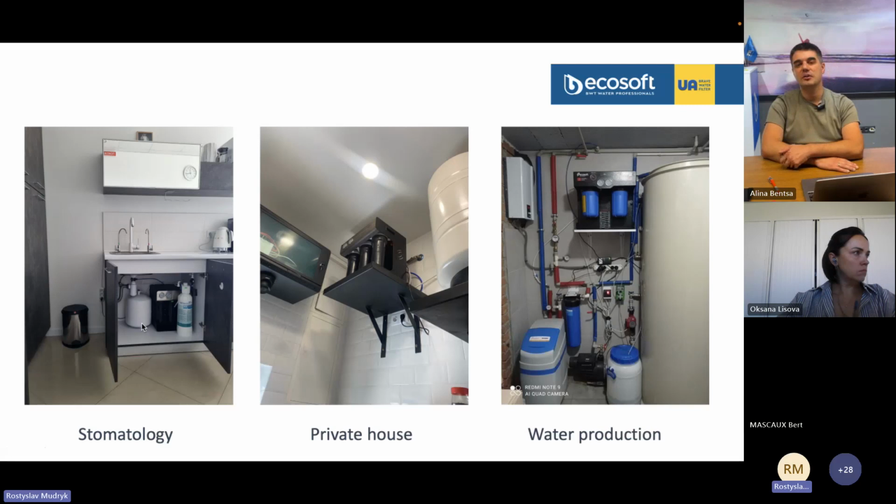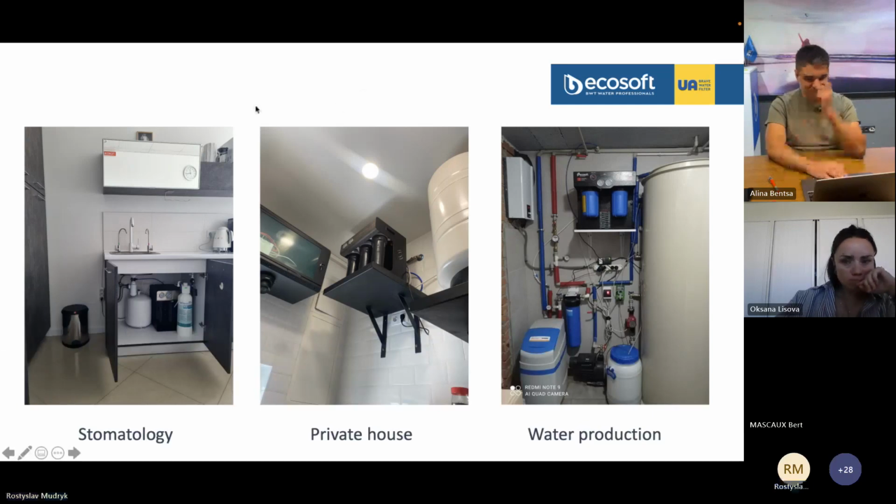You can connect it to the dishwashing machine, because they use quite expensive dishwashing machines, also to sterilize tools, that heat the water up to 80 degrees Celsius. They would require either softening, or they could use the water after Robust 1500. And after the mixed bed, the water is used for the autoclaves or sterilizers. So this is an application where Robust may be used.